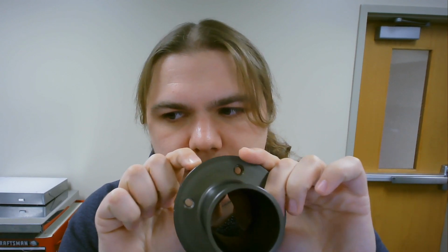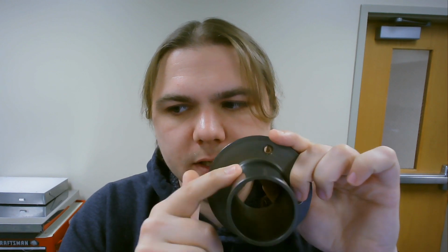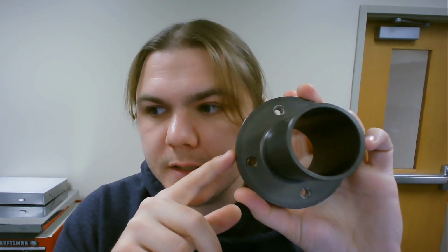The diameter of the fastener hole, if that got bigger or smaller, maybe that would actually control the thickness of the flange from this cylinder here. So if it got bigger, thicker; smaller, thinner. That'd be a pretty simple one to put together. Another thing to consider on something like this is to pattern those holes, so that if they need more or fewer holes, you could simply go into that pattern, change that number, and you would be done.